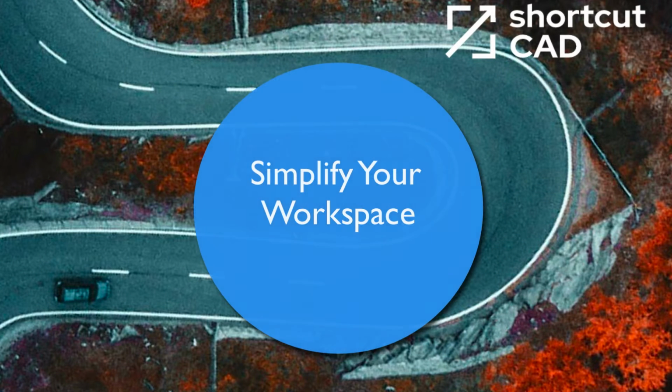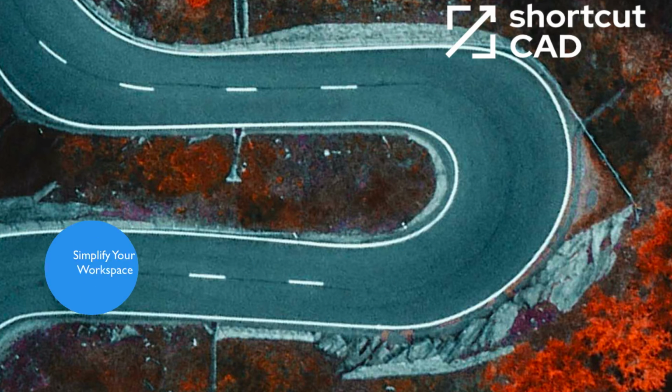In the first module, I'll show you how you can simplify your workspace and essentially declutter so that you can work faster and more efficiently. Then we'll touch on what the Cartesian coordinate system is and how to use the UCS. We'll also start creating a wall detail. I'll show you how to use dynamic input, and we'll discuss grid snaps and lots of other stuff.